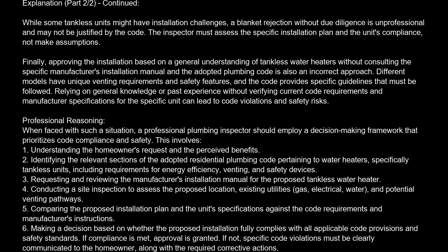Finally, approving the installation based on a general understanding of tankless water heaters, without consulting the specific manufacturer's installation manual and the adopted plumbing code, is also an incorrect approach. Different models have unique venting requirements and safety features, and the code provides specific guidelines that must be followed. Relying on general knowledge or past experience without verifying current code requirements and manufacturer specifications for the specific unit can lead to code violations and safety risks.